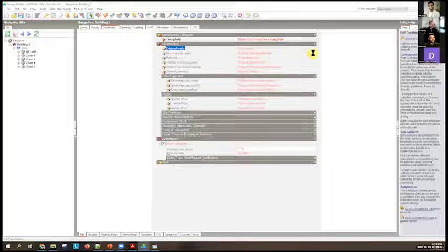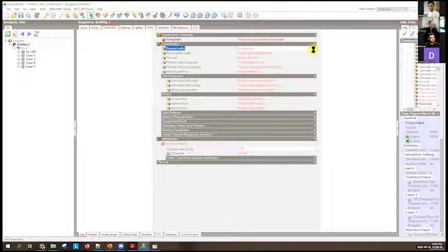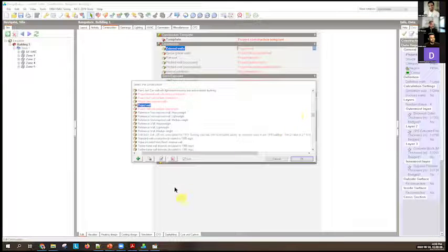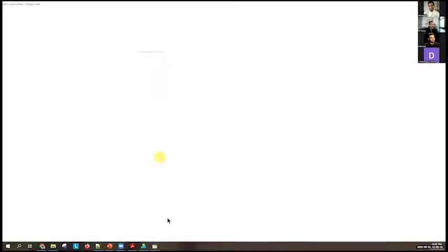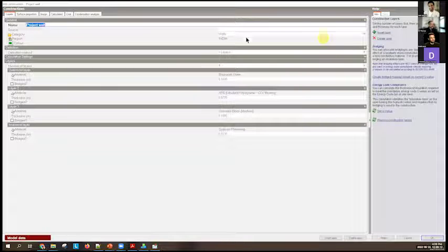So if I pick this project wall, you can actually examine that. That's the edit button there. And you can see what it's made of. Brickwork, insulation, concrete block, gypsum plaster. You can make any changes you want. Now, it's easy enough. You can add layers, remove layers, add materials.